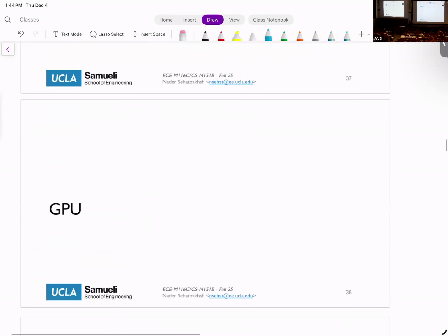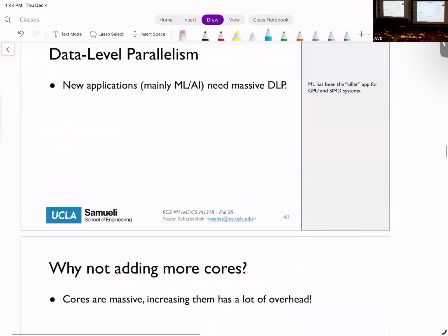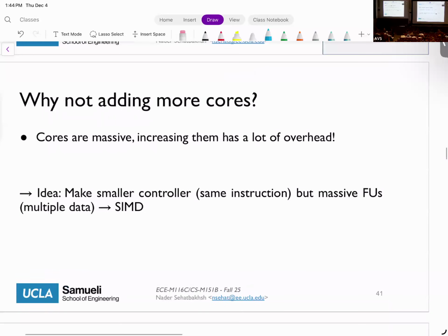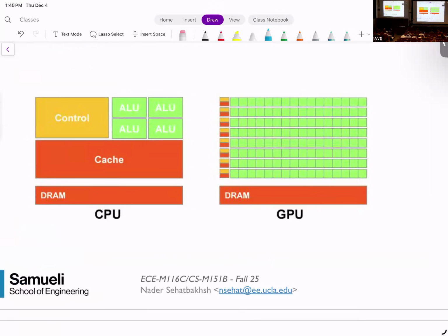All right. As I said, we unfortunately don't have time to talk about GPUs. But in one sentence, if I want to say what a GPU is and how it's different, a GPU is essentially the same pipeline architecture as a CPU, but it does things as follows. In a GPU, your system is one giant functional unit. Your controller, your decoder, your renaming and your reservation station are still there to some extent, but they are very, very small.